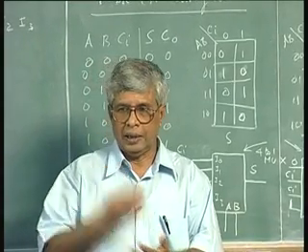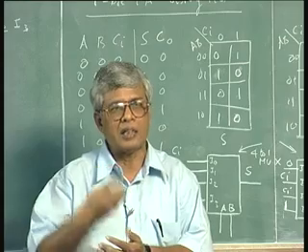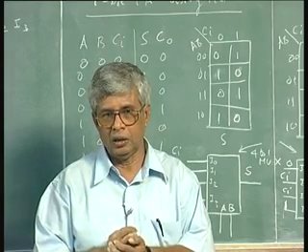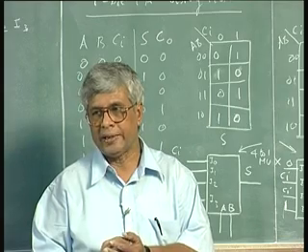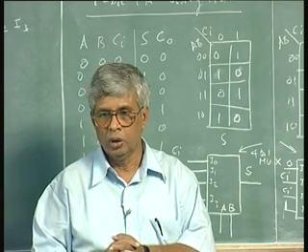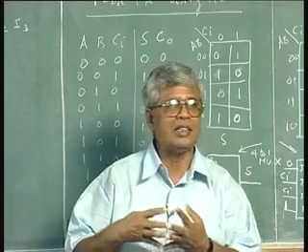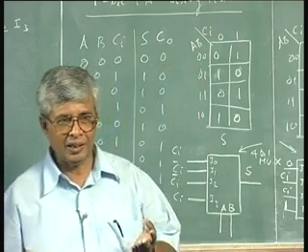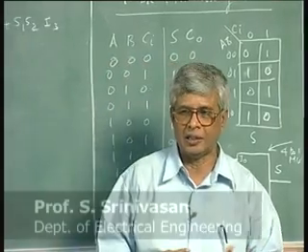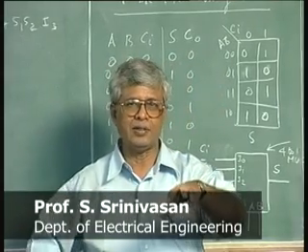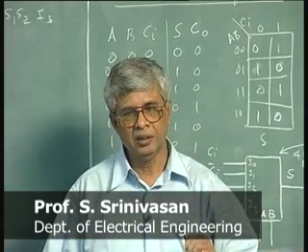So, this tells you there are ICs available which are functionally larger compared to the simple gates, and these will be used in the design of combinational logic. Even in sequential logic, the combinational logic is the steering logic, is it not? Steering logic is combinational logic. So, we need combinational logic whether it is a combinational logic design or a sequential logic design. So, we use these medium scale ICs which have several gate functions in them.